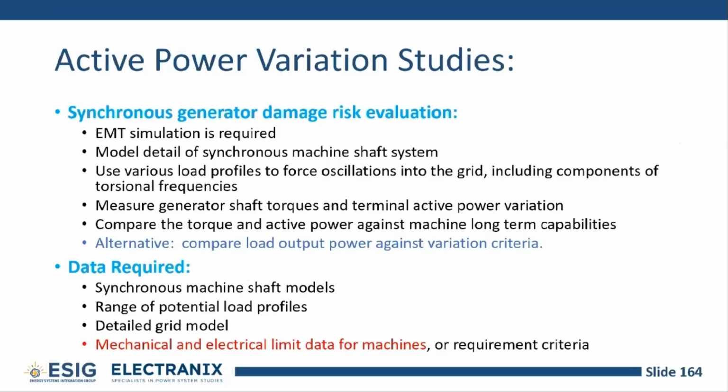And we use various load profiles. And this is where Alex was saying, if you don't know what the load profile is, imagine what the worst one is. We can do that. We can come up with square waves, different load profiles that we've seen. We can do whatever we want, but we can use different load profiles to force oscillations at that load location in the grid, and then measure what happens to the torques on the synchronous machine shaft, and then compare those to the endurance limits for the machine. We know that this might happen forever.